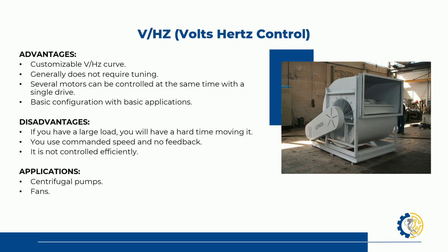The drive, depending on where you're going to command it as velocity, then that is going to respect that velocity instead of modifying that voltage. Okay? Now, what I was saying was, we can control many devices at the same time, many motors, with only one drive, just as long as we connect it in parallel. Okay? No series. If we analyze this, they're going to burn out because we're going to be connecting all the phases. So, no, this is parallel.